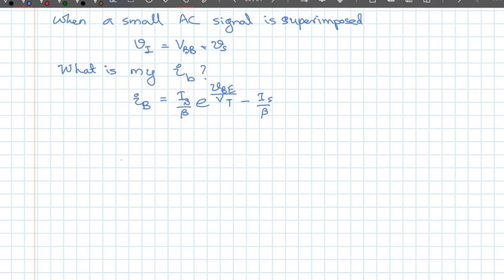the problem there is that the transistor can be either in cutoff, active linear region, or saturation. When in saturation, IB can be arbitrarily large, and the IC does not grow beyond a certain value because it is saturated.